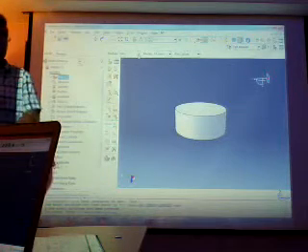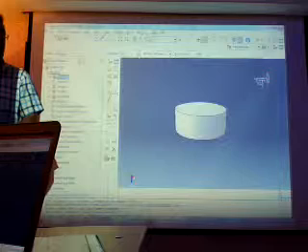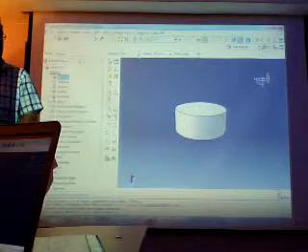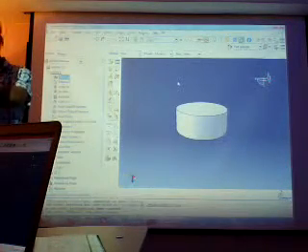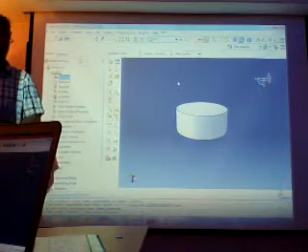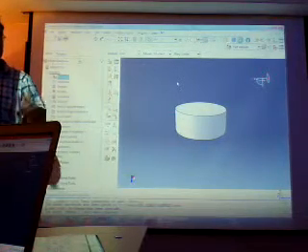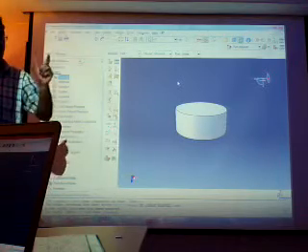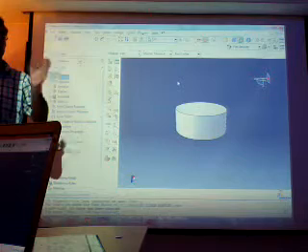And also we need a punch. I think we can put a punch or just put a surface pressure on the back. Surface pressure is okay, but because it is applied on the deformable part, it again increases computational time too much. It is better to take a punch. If we take a punch and give a reference point, we can choose different kinds of loading. For example, you can take velocity, you can take pressure, or anything you want.